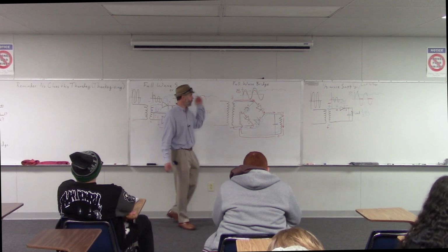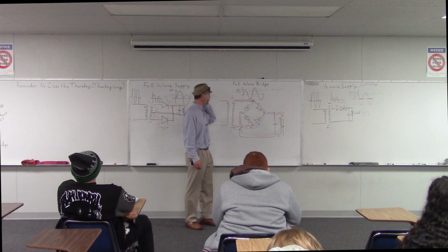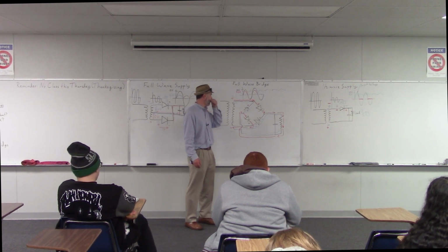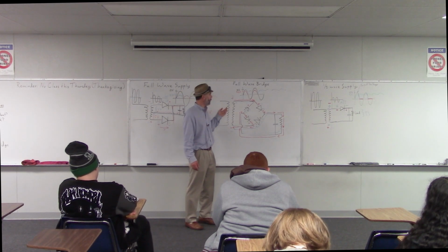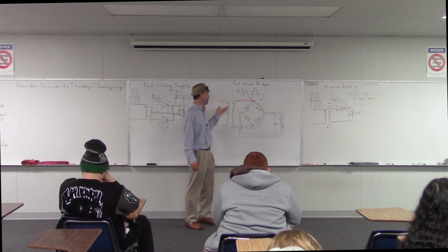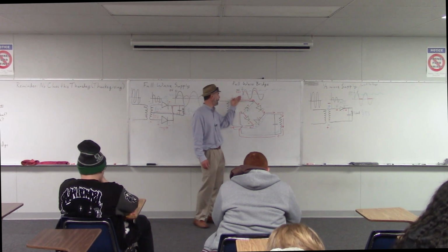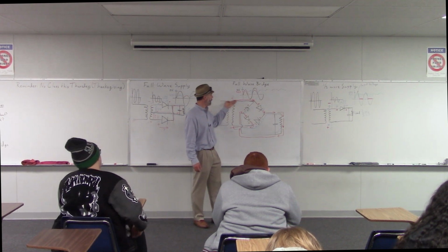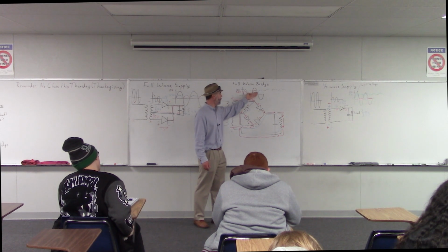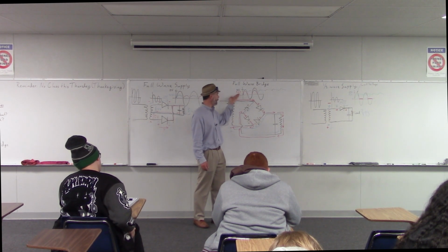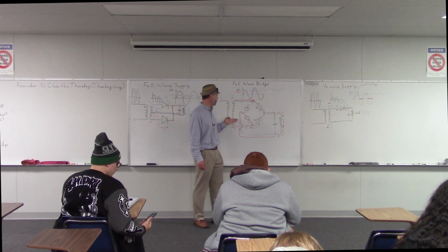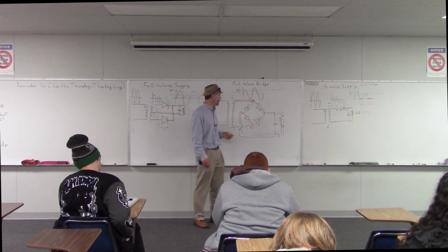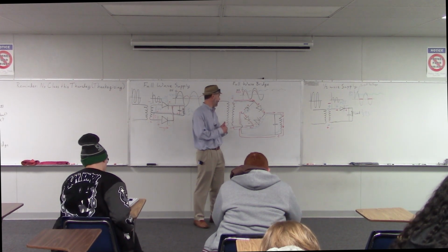And then the full wave bridge supply, it's kind of the best of both worlds. Well, no, it's more complicated, but it's more efficient. It has the full wave output. It's got a higher voltage, but of course it's got more diodes, so it's a little bit more complicated there.